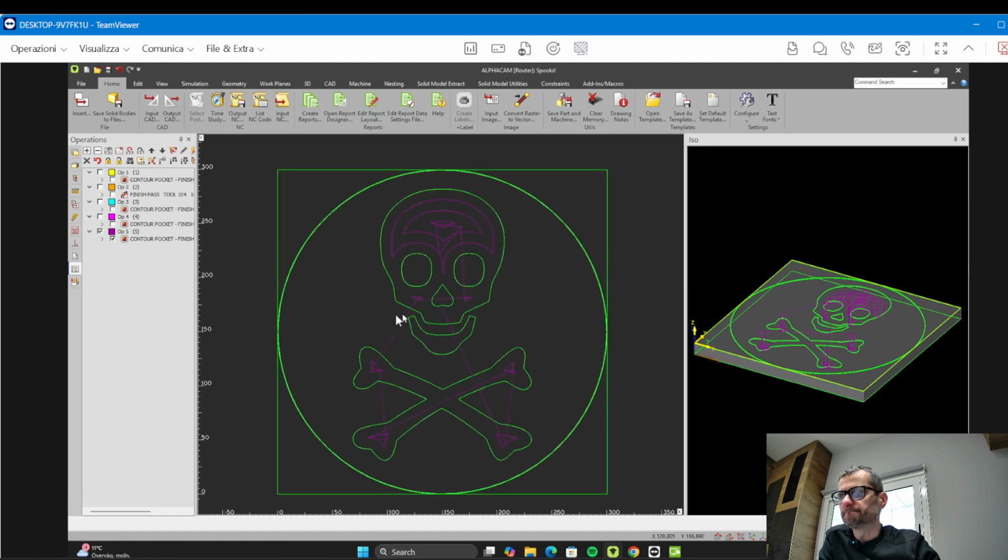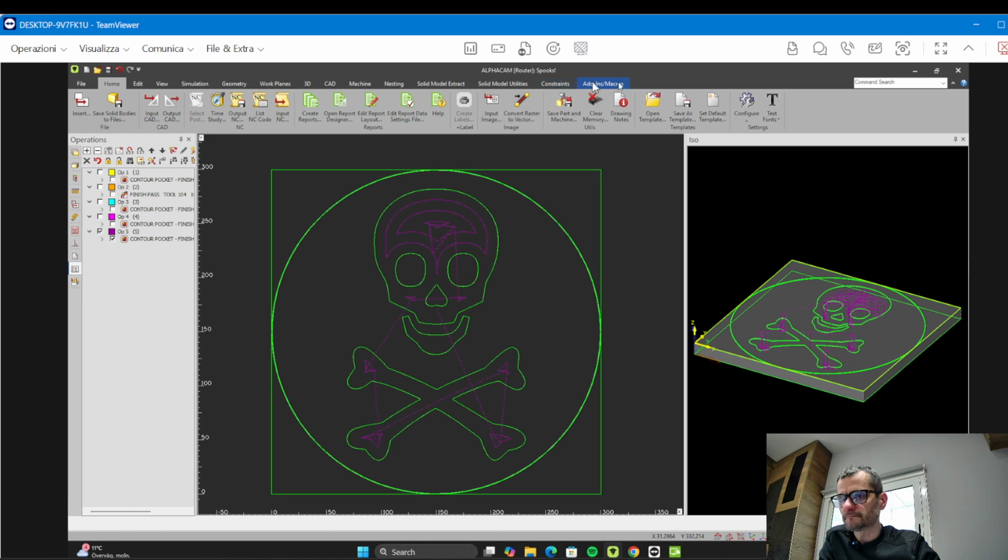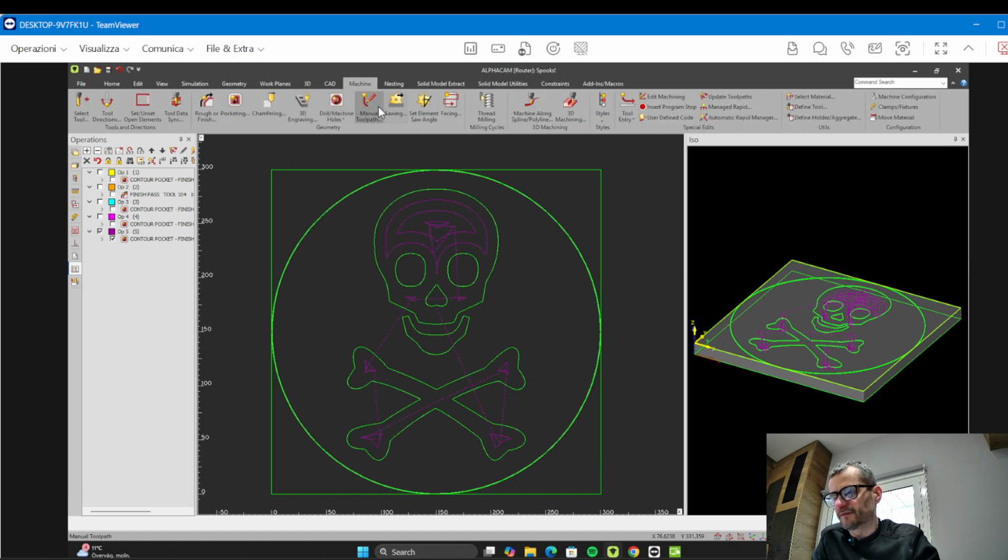Just one. When you create a tool, remember the system works in millimeters per minute, and for distance the system works in millimeters, as you know. In TPA they change one thing about the speed. I don't know why they changed it, but it is like that. So you have to remember that when you work in AlphaCam. I think it's the best way to think about it, because the speed is also in millimeters.